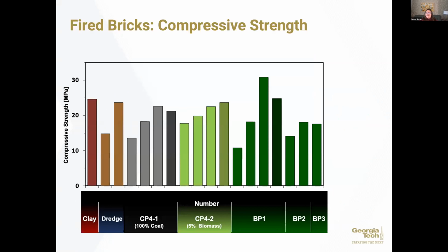At the end of the day, though, we need to know about compressive strength, right? And when you look at this, what essentially we did was we took these bricks and we analyzed them for a series of different climate applications. And for a climate with negligible weathering, you'll see that all of our mixes passed. So everything that we mixed into the brick, we had no trouble with at all. In fact, we believe that we saw some benefit here from the high organic content in some cases, because that is an additional fuel source during the brick making process.